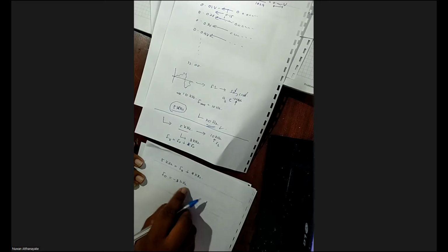Normally, if you have a minus value, when you add it to the cosine or sine terms it becomes a minus cosine or sine, so only the amplitude changes, not the frequency. So you can consider this as 3 kilohertz. Actually, this 5 kilohertz signal will alias with a 3 kilohertz signal.